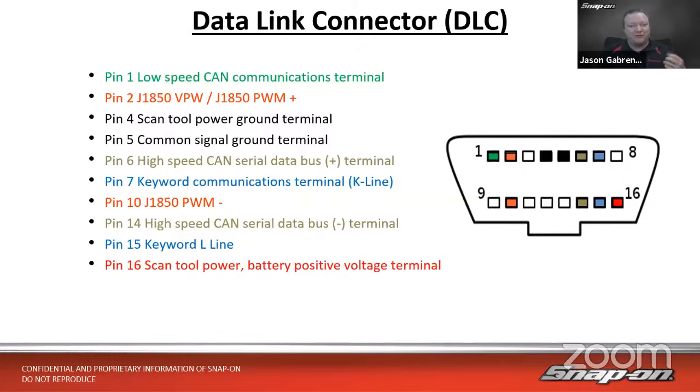So really, if you want to find a communication problem, first off, you need to go through a wiring diagram and see where would I find what modules on what wire, right? So you need to be able to go through that. So that is our standardized diagnostic link connector. They're using almost every single pin on there at this point. It used to just be maybe power, 2 grounds, and then J1850. So that's what, four pins. And now we're using almost all of them. So we've come a long way as far as network complexity on the cars, right?